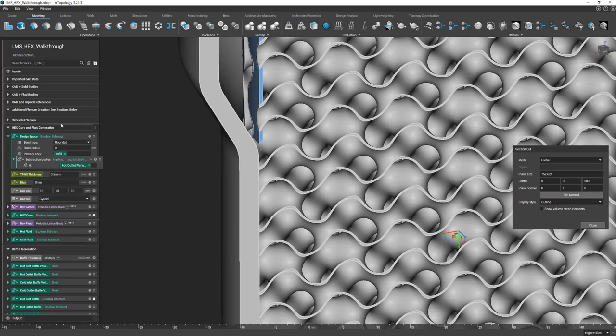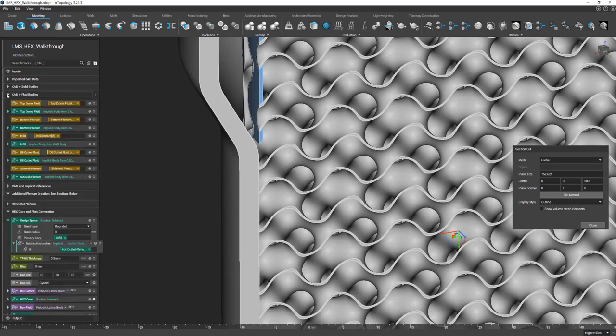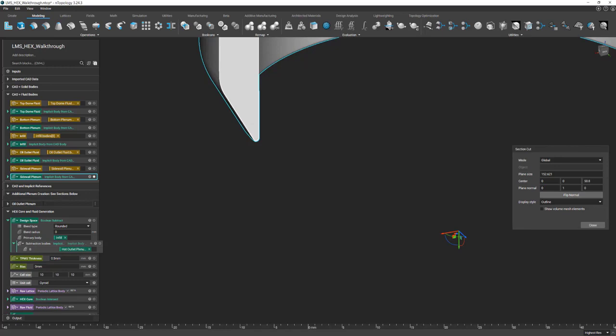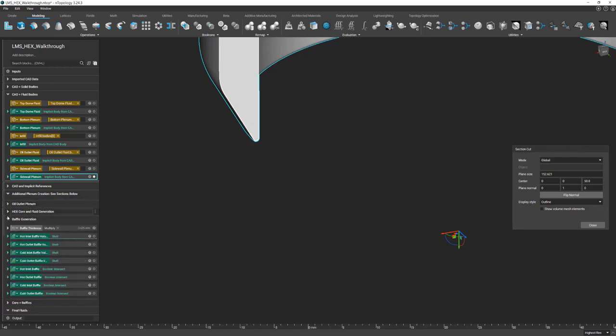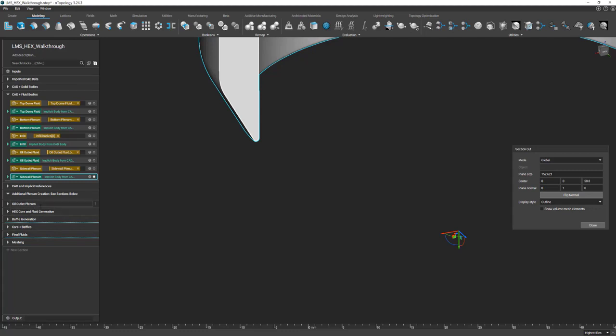For me, the quickest way to go about fixing this was to simply extrude or extend the sidewall plenum region down a little bit. So I'm going to isolate this. I'm going to create a new section for a new plenum under the oil outlet. So I'll click here, right click, add section, and I will call this sidewall plenum extension.